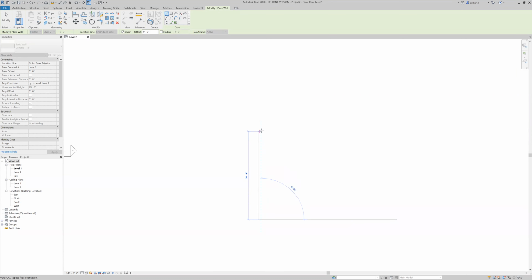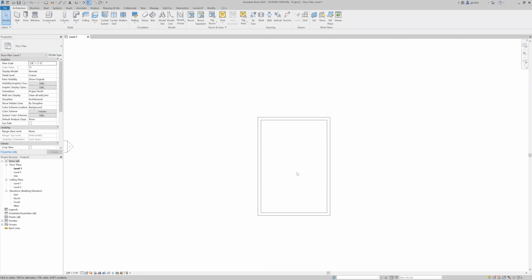You can hit shift and this will flip the direction that the wall is. So you just click one end and then click the second end to complete the wall. And it will continue from where you last left off. So just to draw a box here with 4 main walls, as you can see, it's snapping to and being smart about where you started and ended your last walls, wanting to make it as rectilinear as possible.